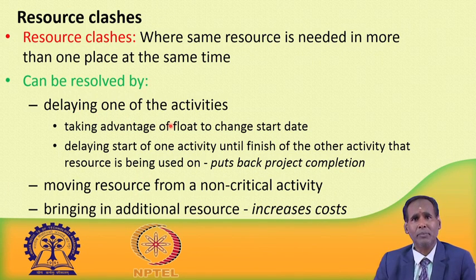First, you may delay one of the activities, so that it can wait for the resource to be freed, so that it can be allocated to the needed activity. You may take advantage of float to change the start date, because I have already told you we can use the float time or the free time, so that the start date can be a little bit delayed. Delaying the start of one activity until the finish of the other activity that the resource is being used on. But this will put back the project completion, it might be delayed.